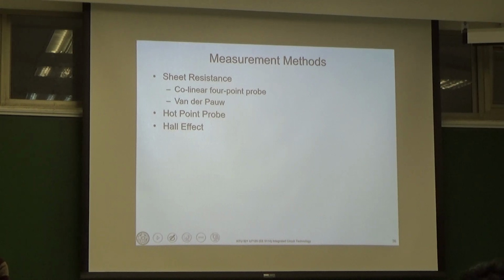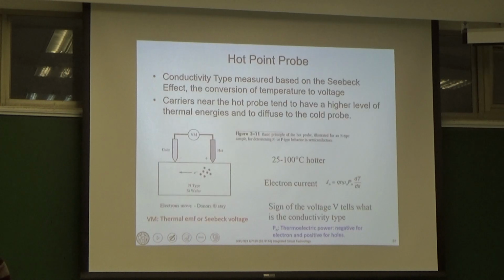So here we will introduce 3 methods related to our wafers. Usually we try to know the resistance, the resistivity, of your wafer. We try to know whether the type is P-type or N-type substrate. So here are 3 methods that we commonly use to measure our wafers.